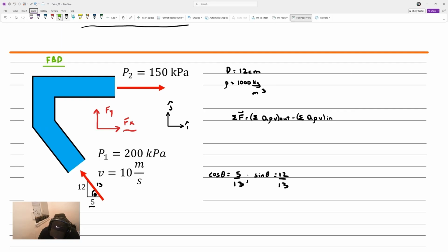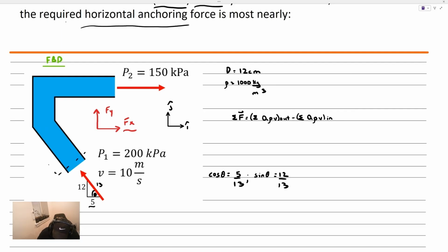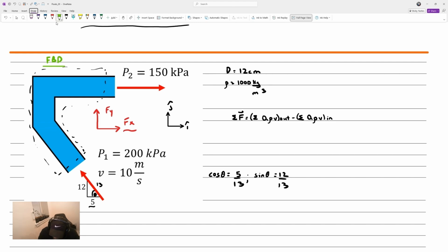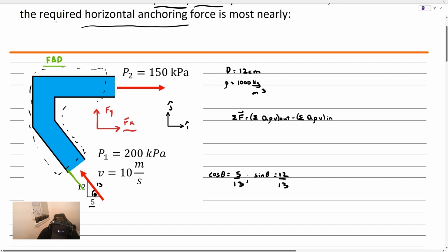Whenever you draw a control volume around a system, which is this dashed line that I'm drawing here, what it does is it frees the body from its surroundings, and as soon as you cut the body, you're introducing some pressure forces, which is what I'm drawing here, a pressure distribution due to the adjacent water molecules pressing onto this. As soon as you cut the body, these are like internal forces in mechanics of materials. You have a pressure force. Its height is P1 acting over an area A1. And same thing on the top, right?